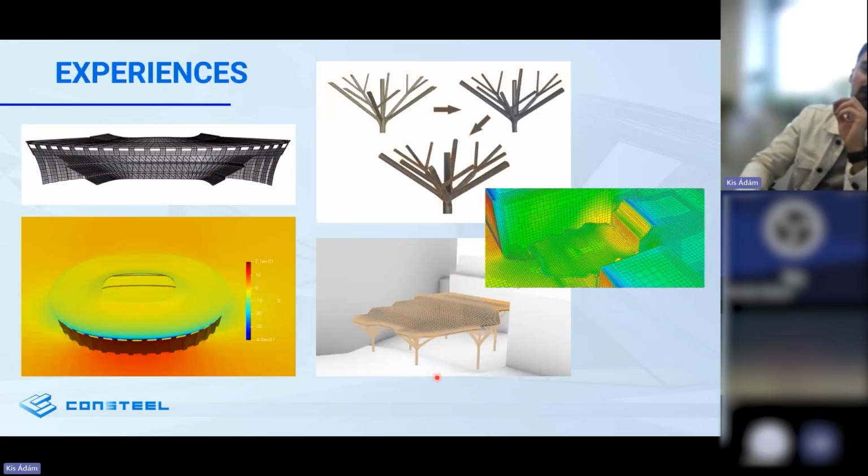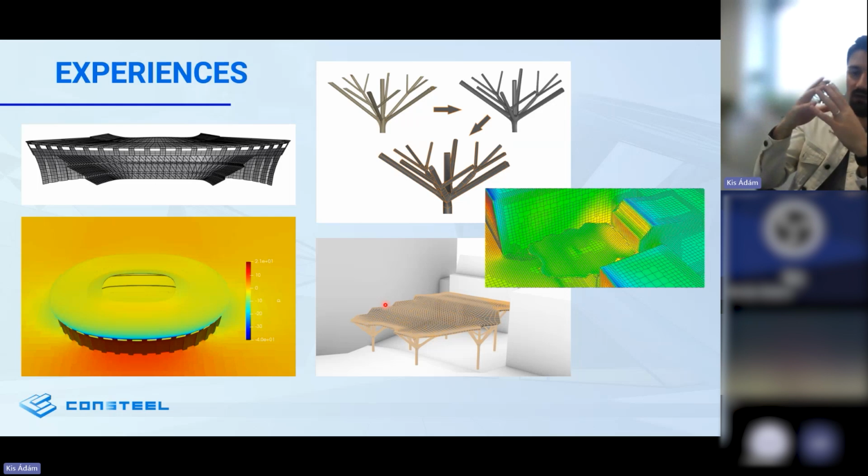Because what are our experiences regarding using these types of beam member structures and other, let's say, landmark type structures? This is what I would like to talk about quickly, because we tried to reach the limits of this tool, these simplified Reynolds-averaged Navier-Stokes based approaches, which are capturing and modeling only the main vortices around the building.